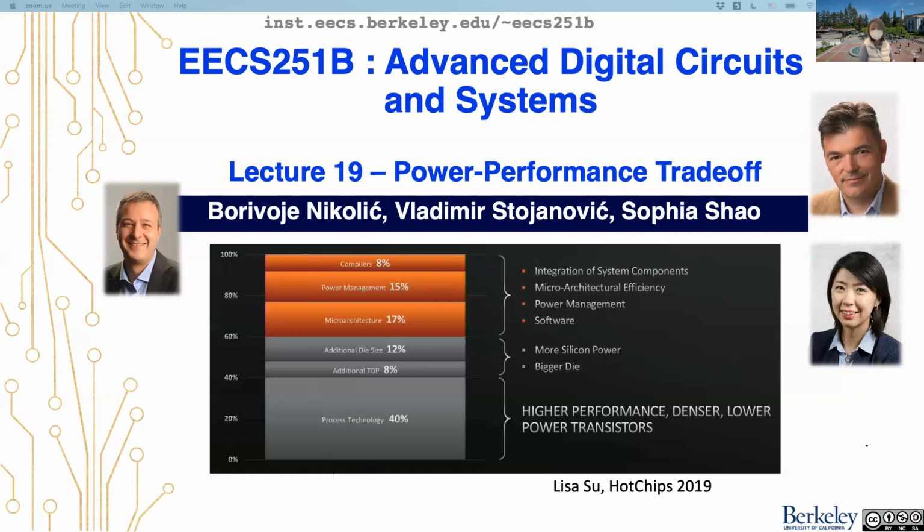We don't have the time to cover this in this class, but I also teach a domain-specific hardware class, especially about domain-specific architecture. One of the major motivations for domain-specific architecture is the power problem. We cannot power all of the out-of-order fancy microarchitectures with the current power budget, so we want to use our power budget more efficiently. If you understand power, you can see the reasons for the transitions in the past 20 years, why different companies and different designs made certain optimizations. This is very fundamental when we approach modern designs.